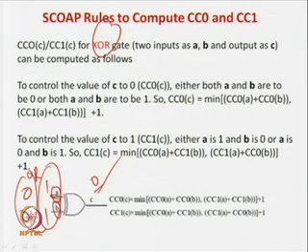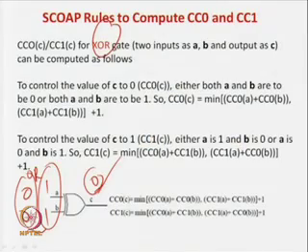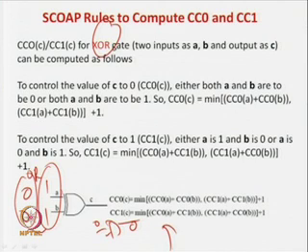But for the XOR gate, it is somewhat different. You cannot use one input to get a 0 or a 1 directly. For an AND gate or an OR gate, if you control one input, you can easily get a 0 or a 1 at the output. For AND gate, for 1 you have to apply 1 1, but for a 0 you have to apply a 0 at any of the inputs. But for the XOR gate, you can never say that one input can control this value. So, for an XOR gate to get the value of 0 or 1 at the output, you have to know both the input values. This is unlike the AND gate, where a 0 implies that the output is a 0, and the OR gate, where a 1 is a 1; even if you do not know the other input, you know that the answer is a 1.